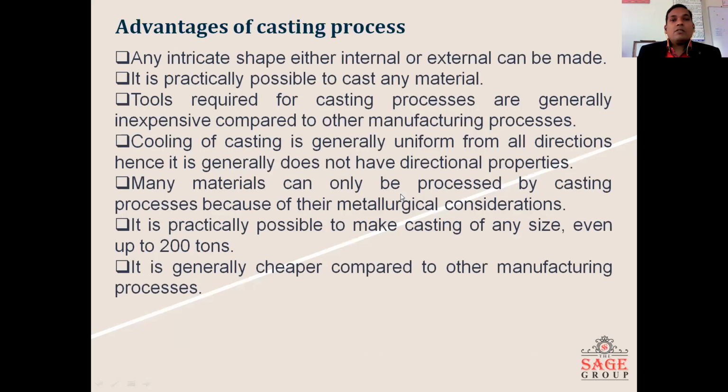Now, what are the advantages of the casting process? So any intricate shape, either internal or external, can be made with the casting process. It is practically possible to cast any material. Tools required for the casting process are generally inexpensive compared to the other manufacturing processes or production processes. Cooling of casting is generally uniform from all directions. Hence, it generally does not have directional properties.